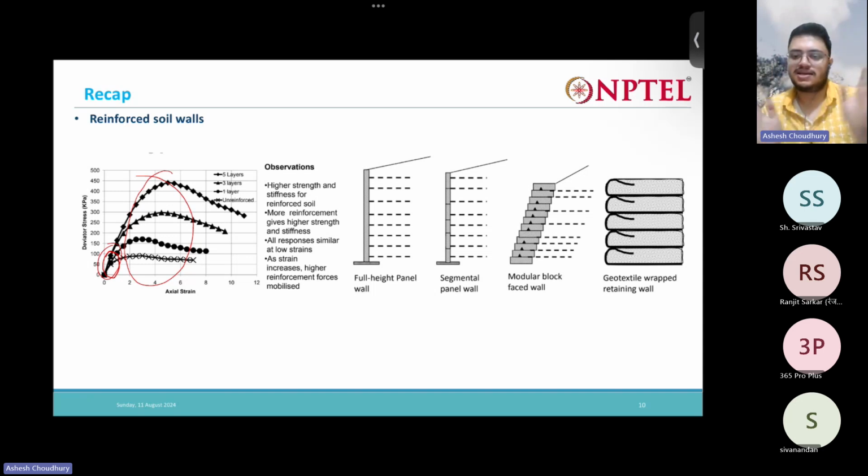Soil doesn't have tensile strength. No tensile strength. We do not consider soil as taking tension in this case particularly. We consider it only having compression. Generally, when we explain these things, it has some tensile strength, very minute, so we generally tend to neglect that. Soil does not have any tensile strength. It is not that soil is taking some tension at the beginning, and when it is not able to take the tension, it gets transferred to the reinforcement. Not that, but what is happening is that enough strain is not getting generated in the reinforcement itself. That's why this load transfer is not happening. That is the reason.